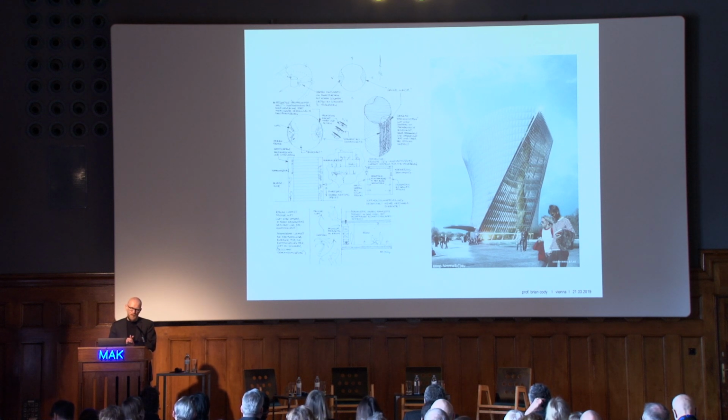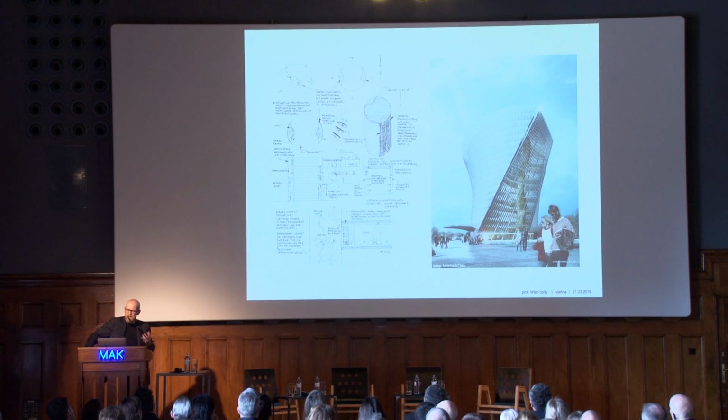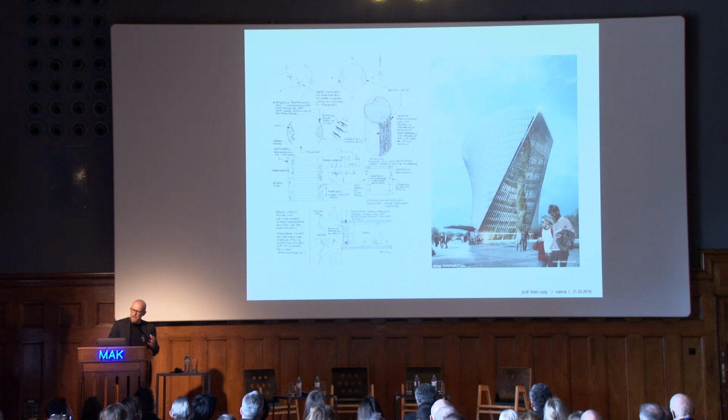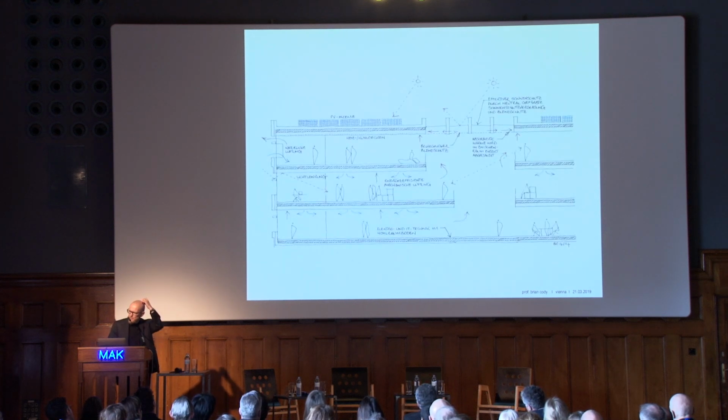So for here, that was Gateway Gardens in Frankfurt. The question was, it's near an airport, it's a really bad environment, a harsh environment from the airport, from the Autobahn. So how does this building breathe? How does the building get air? Of course, how do the occupants get air? And so we developed this form by introducing to the mass two atria. One is delivering the fresh air, the other is taking out the extract air, taking the air in at the top. And basically from there we developed these forms, of course, spatial connectivity in a skyscraper and other issues too. And from there the design proceeds.